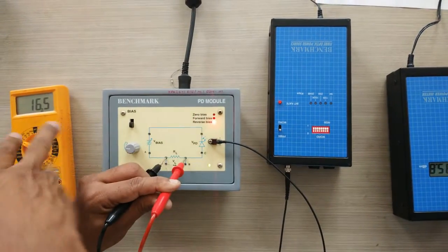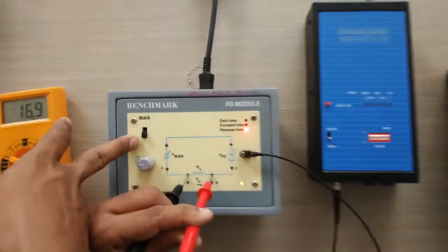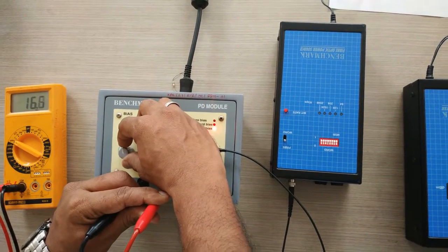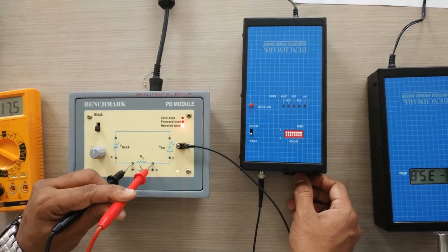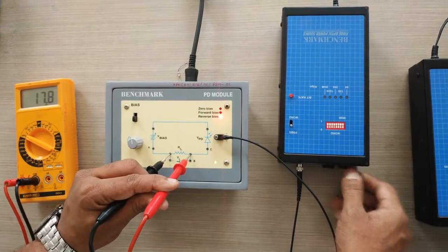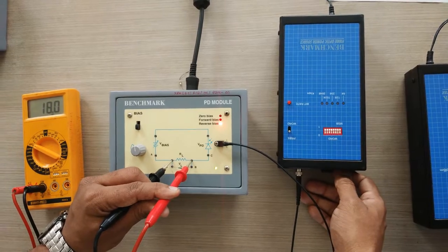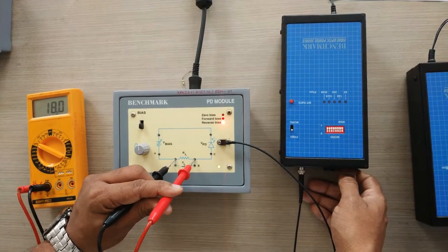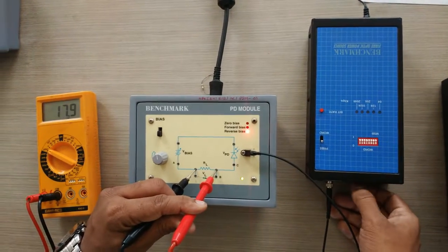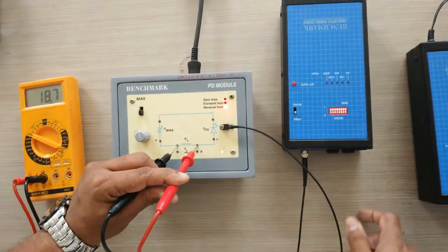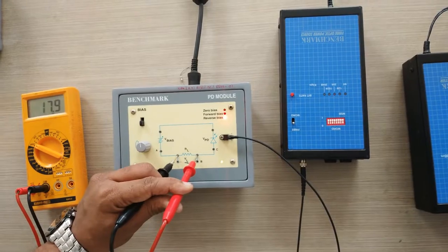So I have switched the bias switch to the reverse bias condition. Now I have fixed the voltage bias constant first, and I am going to vary the power level. Okay, the optical source power level I am going to vary. You can see the voltage differences here, right? It is increasing, right? I'm increasing the power level, and by varying this power value you can plot the power and voltage characteristics of this photodetector in reverse bias.